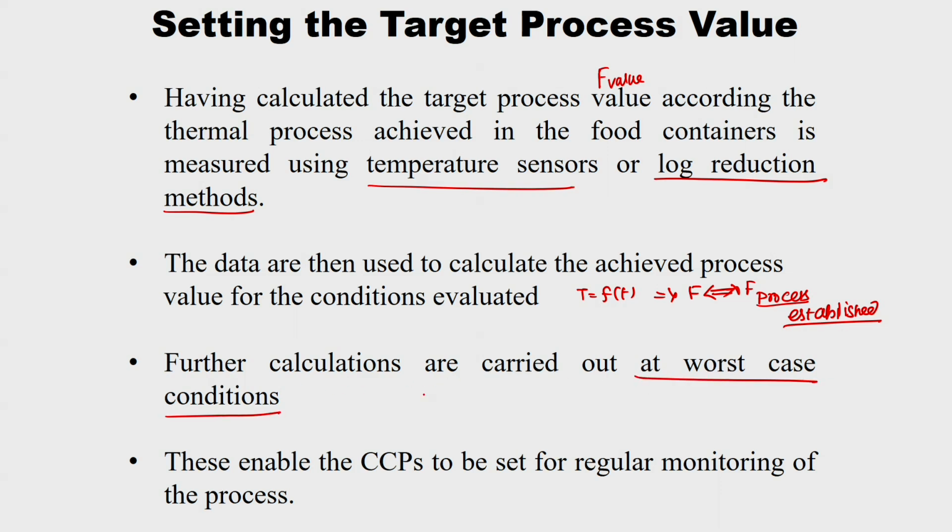So this is where a little bit of experience is needed, as I told in the food microbiology section itself. As a chemical engineer, I know thermal processing better, but food microbiology we don't have that deep knowledge, only basic knowledge. So properly experienced personnel should be employed to establish this F value, because it needs the food microbiologist as well as the thermal processing engineers, both of them together, to come up with this process.